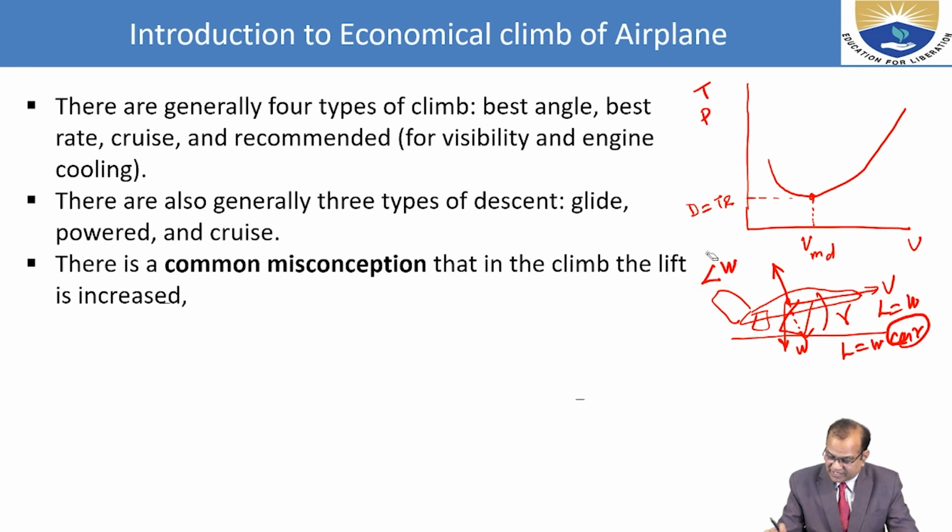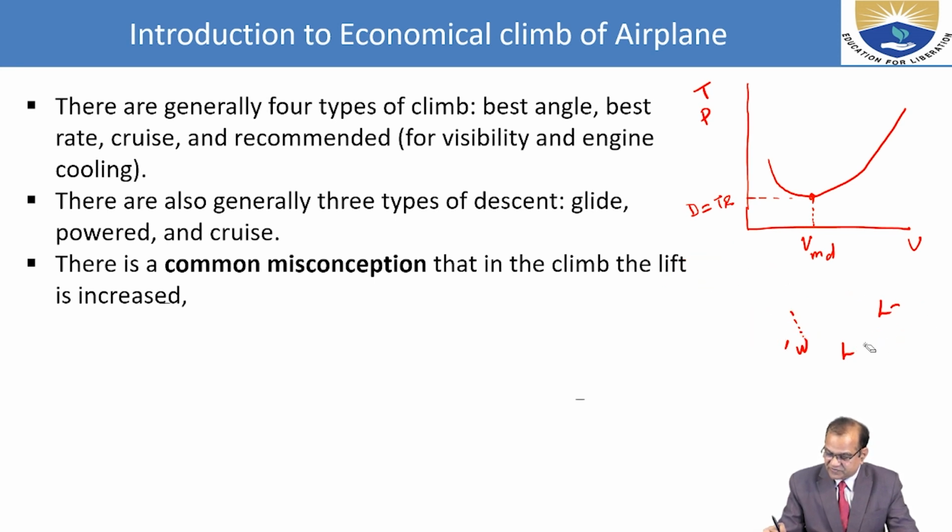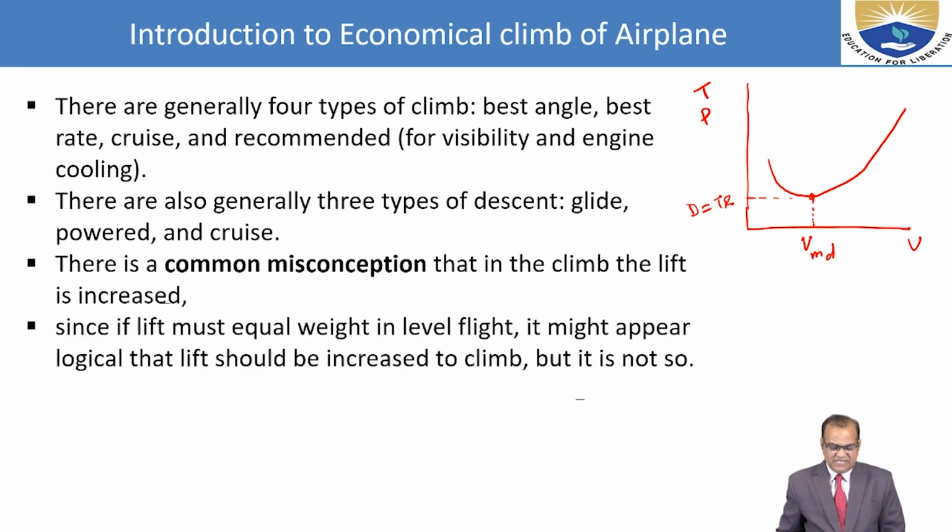So we have to understand that for the climb case, it is not necessary that the lift is higher. The lift requirement is lesser than the cruise condition. Since lift must equal the weight in level flight, it might appear logical that lift should be increased to climb, but it is not so.